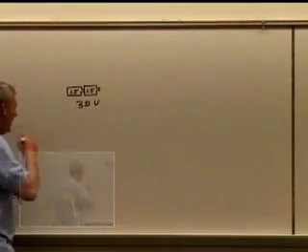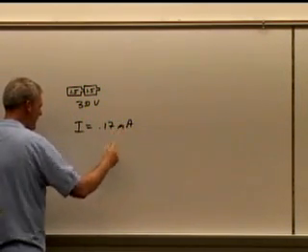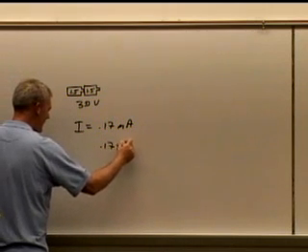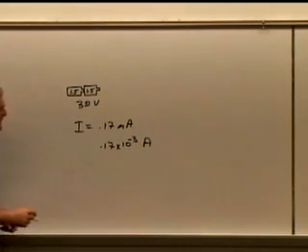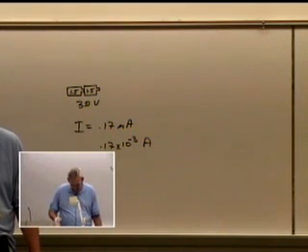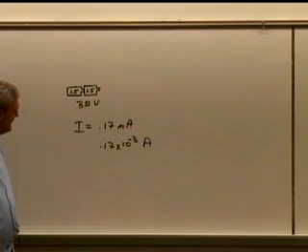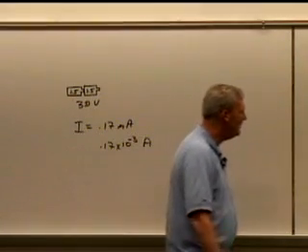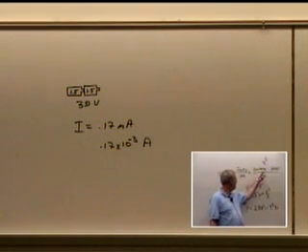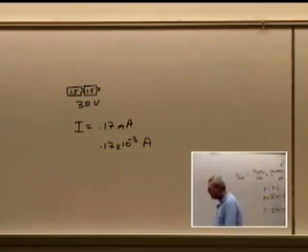All right, the current inside this little thing is 0.17 milliamps. Now, milli would be 0.17 times 10 to the negative 3 amps. Okay? And it says, how much charge flows in the circuit and how much energy does the battery deliver to the calculator circuit? Okay. What did we say energy was again? Coulombs times volts. So we need the charge. We need how much charge?